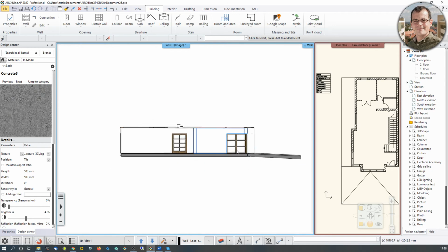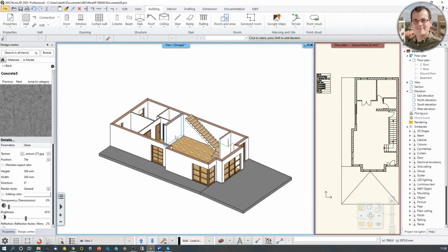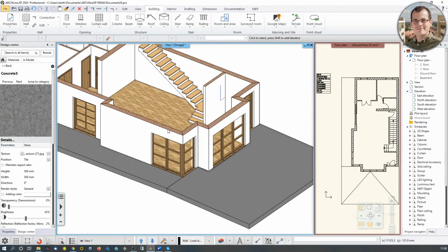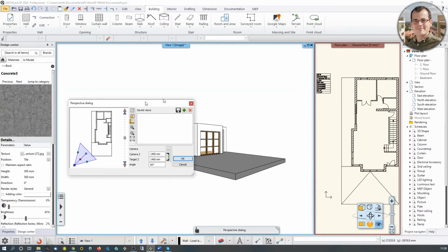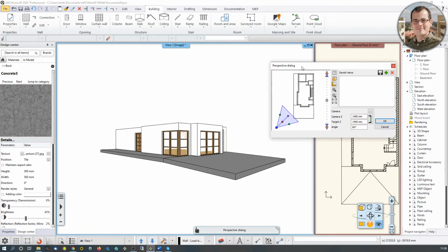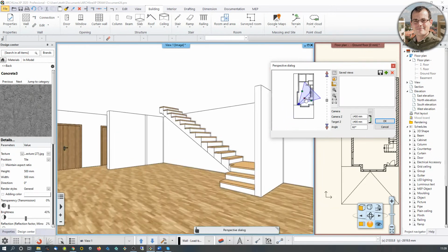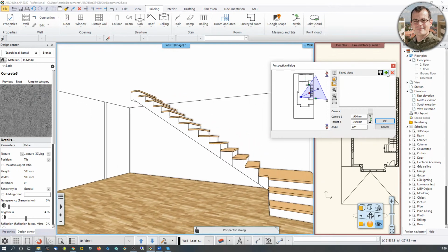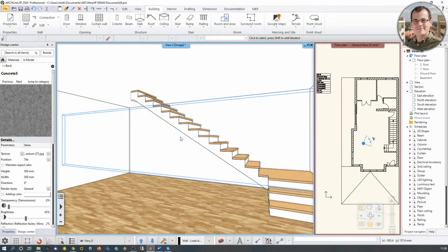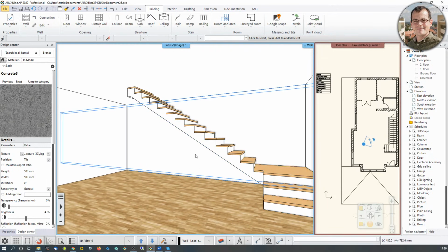What's wrong with that? Well, it's nothing wrong, actually. This is an axonometric view, meaning that no matter how close I get, the distances would not get shorter. So I have to jump into something that we call a perspective view. Now the perspective view can be achieved with this eye icon. And now the software tells me that this is where I am, that's where I'm looking, that's the model. So that's what I see. If I click on the red marker, I can drag my camera closer, and now I see the staircase just like that. Okay, that's going to be good, so I'm just going to hit the plus icon, and now I have a view saved over here. Later on we are going to return to that, don't have to worry about that.